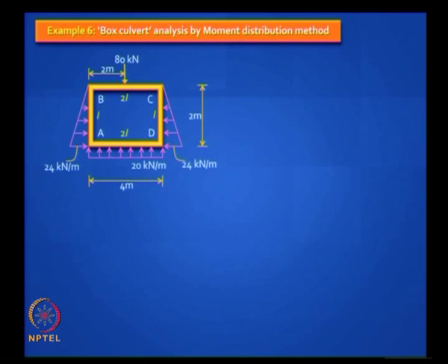And if you had a concentrated load in that box culvert, say due to your vehicular load coming, then it will be balanced by a soil pressure from below, which is conveniently assumed here to be uniformly distributed. And you could have, what are those triangular pressures you get on the side? Yeah, they come from the soil, and maybe if there is water around there. So it is a self-equilibrating system. This is a self-equilibrating system, you do not talk about supports here, okay.